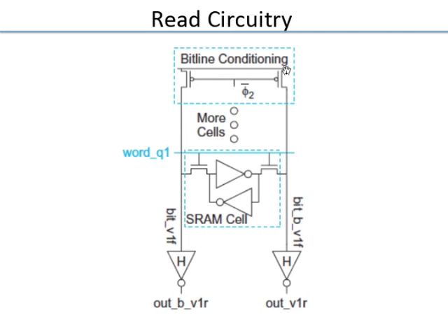At the top of the pair of bit lines, you have two PMOSes which precharge the bit line. Before a read, you precharge it and let it go to 1 volt, or whatever VDD is. Even if you do not precharge, it would work, right?